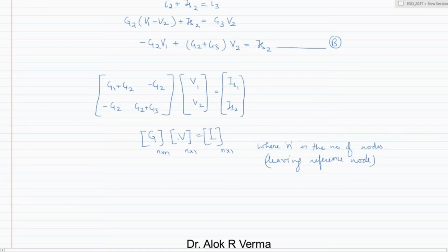This is voltage at the given node or the node in the circuit, and then net current. Okay, so here in this particular representation, these IS1 and IS2 are the node currents. So basically at a given node, if there are different current sources which are connected to that node, the total sum of all the currents will be taken as IS1, basically the source currents, which will appear in the right side vector in this matrix representation.